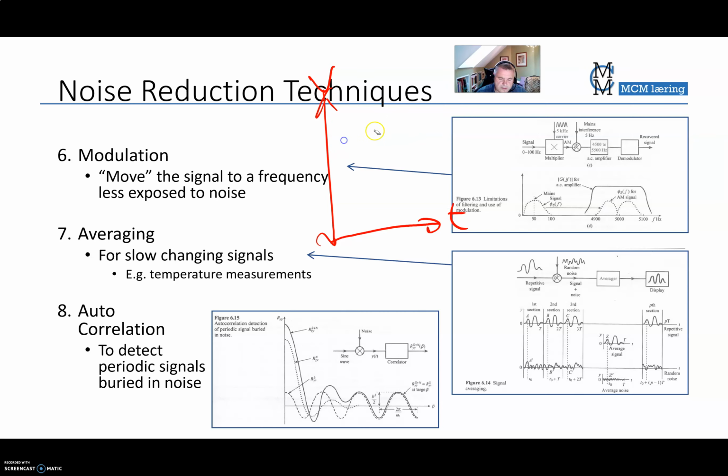So you do the average over a given time interval in order to remove the noise, and that would actually be to remove high frequencies. So it's a form of a low pass filter, sorry. Because if you take the average, you remove the fast shifting components of this noisy signal.